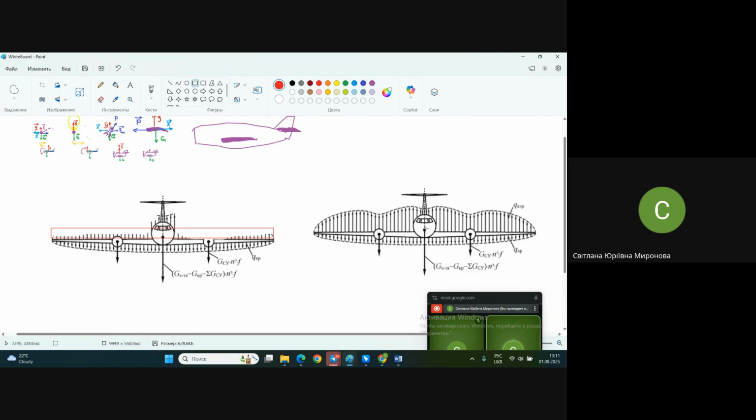It's not bending moment. It's only about the shear forces, so-called. No, it's not shear forces, it's load. So shear forces respond to the loads. That is external loads to the airplane: gravity loads and air loads. And the loads may be distributed even equally, as I drew here with this red line.